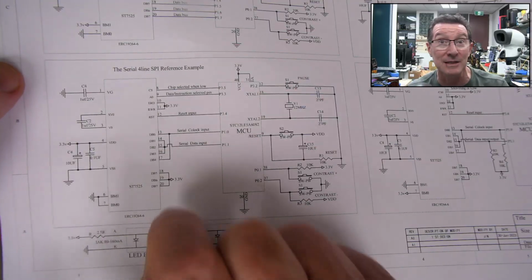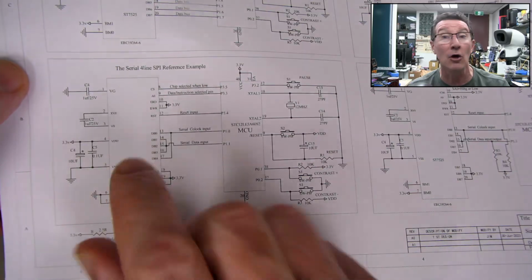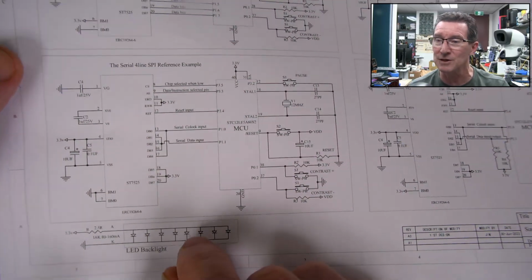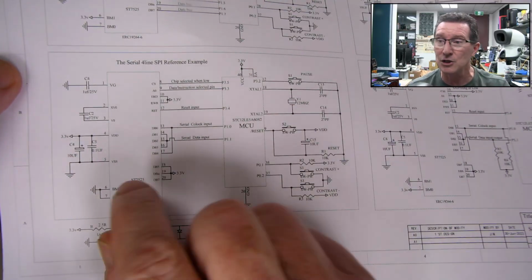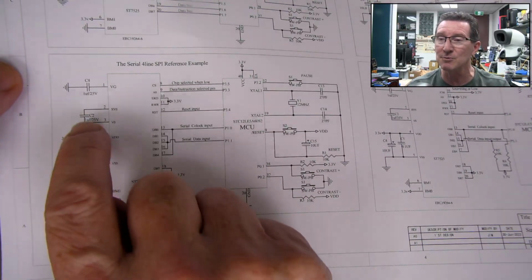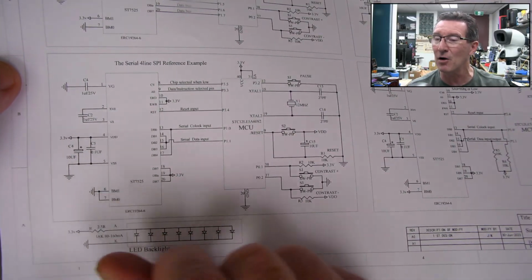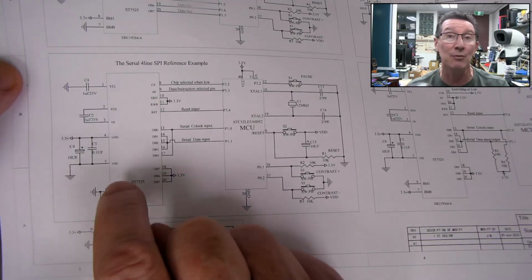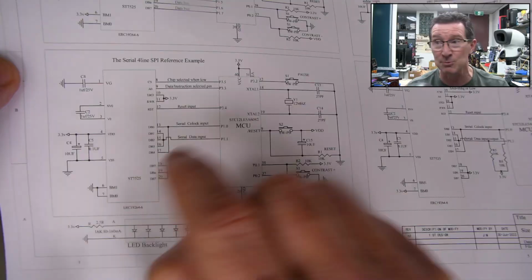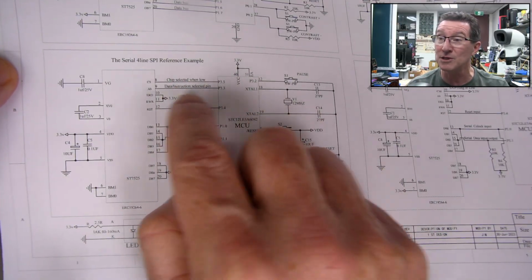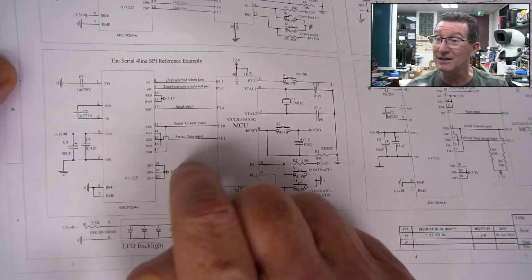This chip is actually easier to drive than the previous one. Like, you need a lot more external caps than this one. So this one's actually better. It's got built-in capacitors which generate the various bias voltages and things. But still need a couple of external caps there, just the bypass in there, and tie a couple of pins here which select the mode. I won't go through the complete data sheet, but this selects the SPI mode, and then chip select, and then data instruction select pin on A0 there.